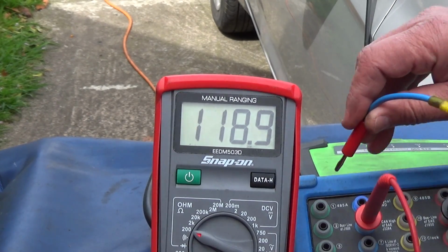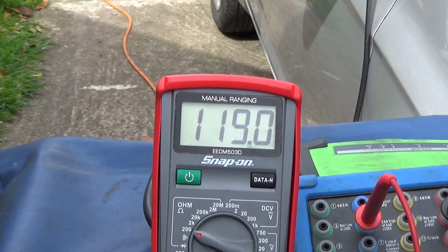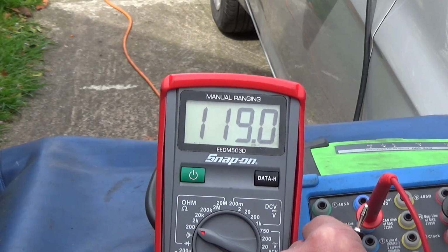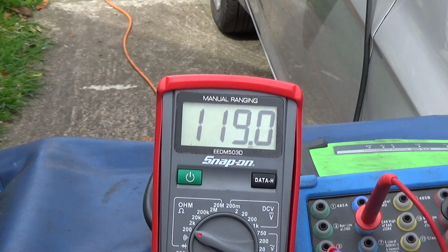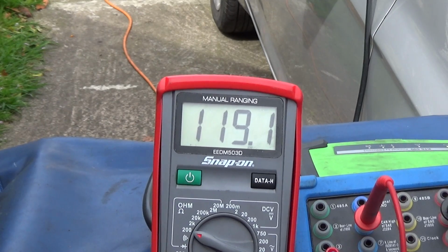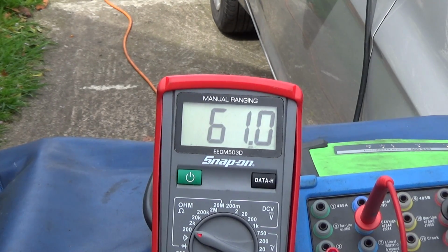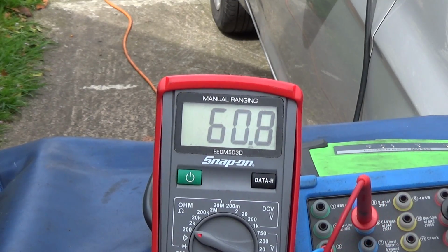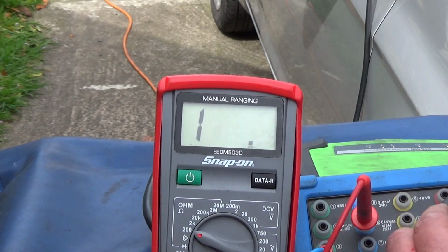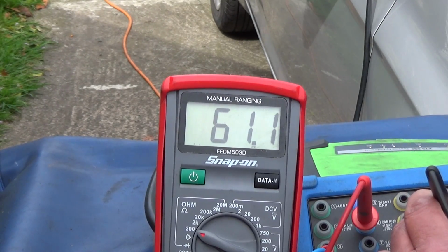And what I'm going to do is go to my chassis ground, which is pin 4, and short the high speed CAN out. Actually, before I do that, I'll plug the modules back in. I'll plug the engine ECU back in so we can see we've got 60 ohms again. So we've got 60 ohms back. I've got one wire to my chassis ground, and all I'm going to do is short it to ground.